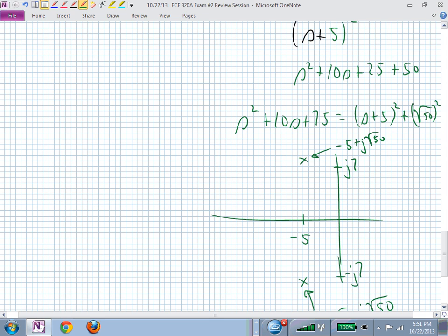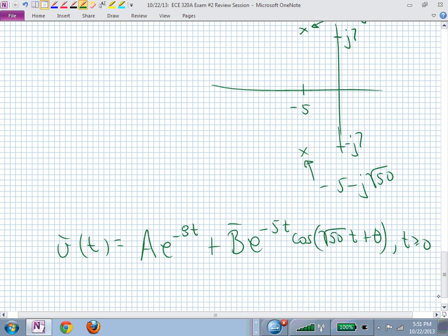That gives me, whoops, scroll up. It gives me my frequency on the cosine. Is that making sense? Is that helping? So really, you look at your denominator and you factor it. And once you have all those poles identified, now you should be able to define what your structure is. You just look at those poles.